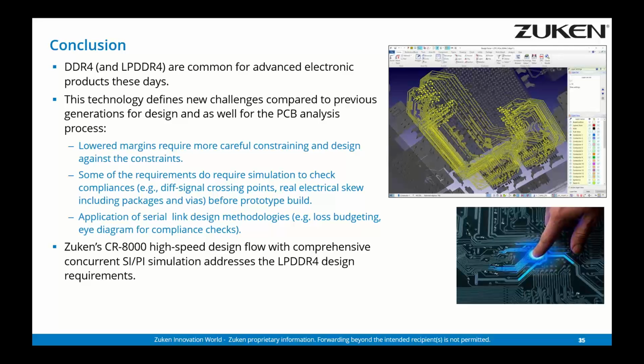We have new design methodologies, which people are probably familiar from PCI Express, but not from memory interface design. That's supported by CR-8000, so we have the high-speed design process in place. So we have comprehensive support for constraining and concurrent analysis featuring signal integrity and power integrity to allow you to implement low power design successfully.